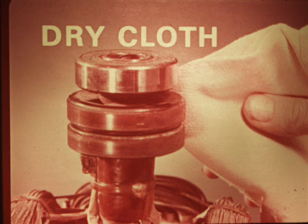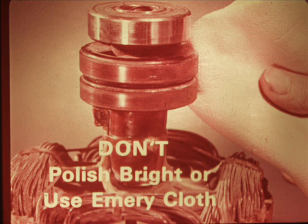Clean the armature slip rings with a dry, lint-free cloth if necessary, or fine 240 grit sandpaper if there's any roughness. Use a very light touch. Be sure to remove all grit if you use sandpaper. Don't, however, attempt to restore their original bright finish, and don't use coarse sandpaper or any kind of emery cloth for the cleaning job.